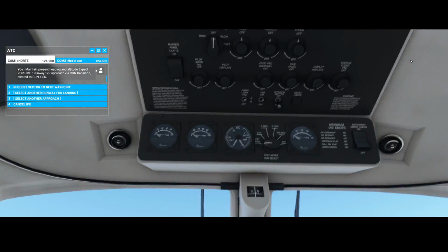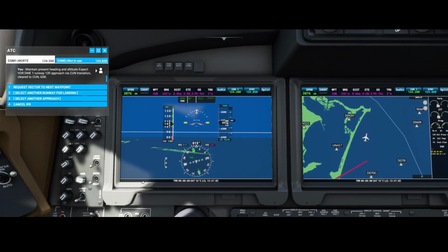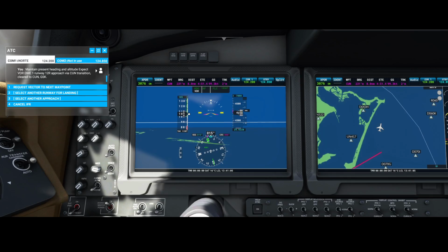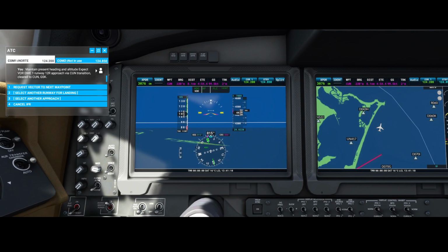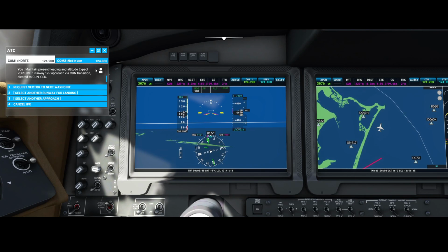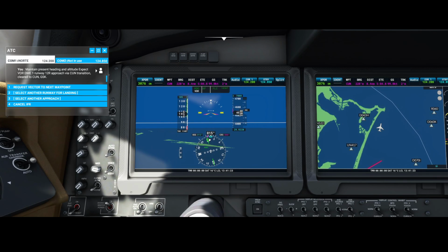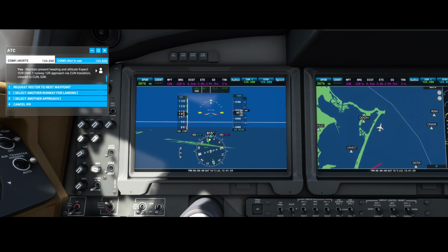So let me go back to the autopilot, and to do that, it's really easy. You simply press, as you might have guessed, the nav mode. What you need to be careful about is that in some cases the nav mode doesn't work, like in my case, right? It continues to fly to 15. If that happens, then you need to change the option here to follow GPS. If that's not the case, like in my scenario, then it won't use the navigation option.